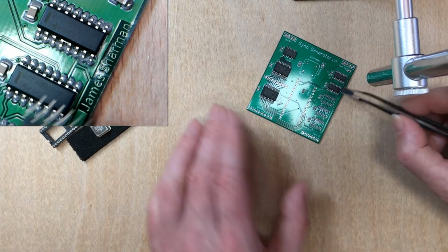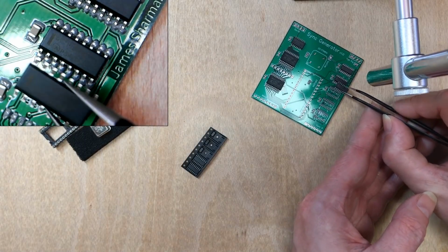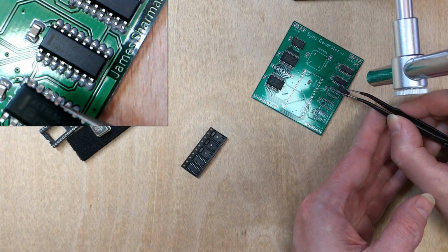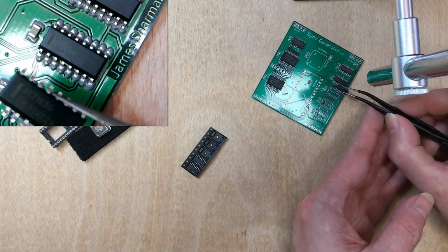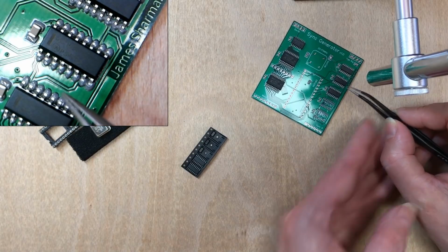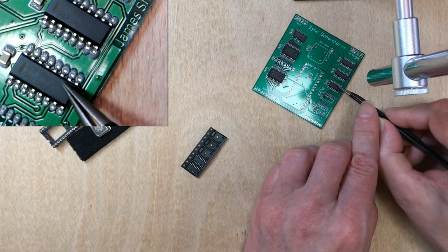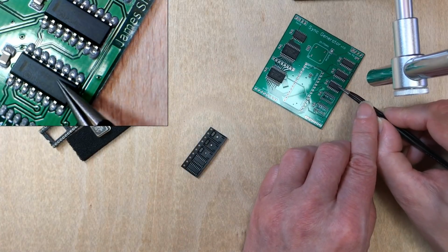And I've had a couple of issues on the breadboards, which I suspect are the propagation delays on the HCT components or VLS components not being quite fast enough. 25 megahertz is right at the top of what the HCT components are capable of handling. In fact, I think I'm using some of them slightly out of spec.